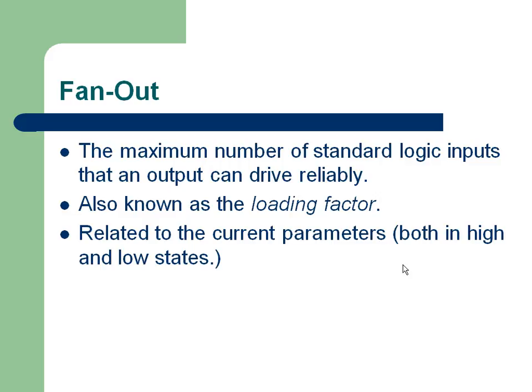You would find that the total logic will work correctly. You give all the multipliers, adders, all the inputs, and you find the outputs correct. But let us say you don't use this DCM, and instead use some other clock which you generated out of your code. In your code, you set the clock to 0, and after some rising clock you create it as data, and if you drive with this one, your total code will misbehave. What is the reason for it?